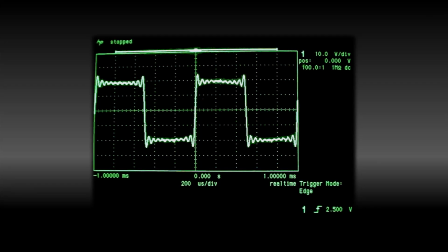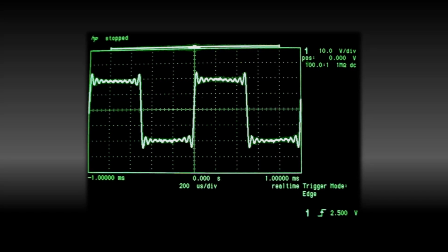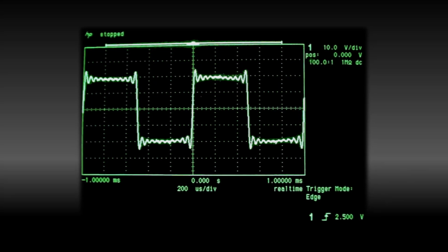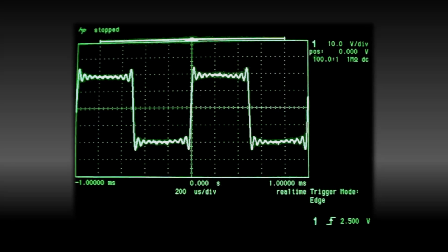When it comes to hard clipping specifically, or making the highest and lowest points of a signal completely flat, well, that actually cannot exist in the analog realm. You can get really close, but there's always going to be some amount of overshoot or undershoot because you can't make a right angle, or damn near a right angle, when it comes to an analog signal.